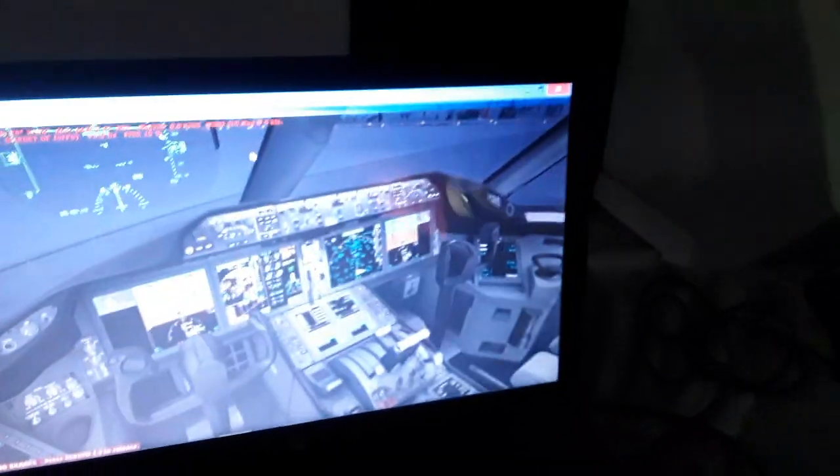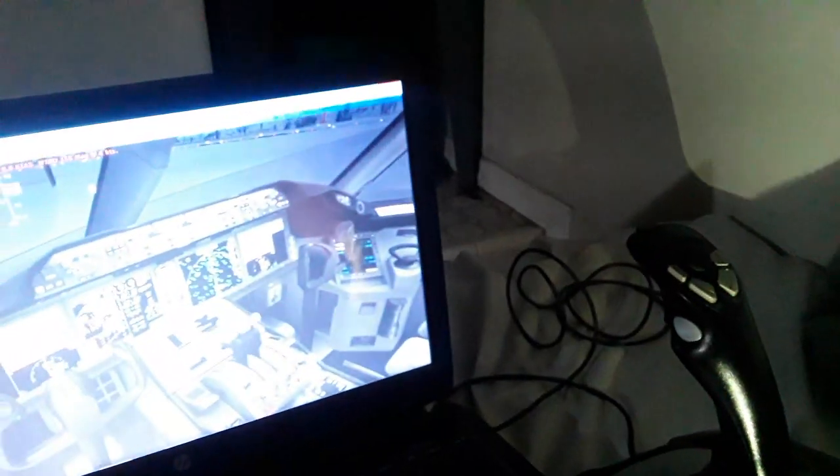So the fuel mixture adjustment is made automatically by the FADEC. Over here when you move the thrust levers, you command the engines automatically. So the FADEC also controls engine start and shut down. As I told you, fuel mixture is automatic, and also the circulation of the fuel, oil and lubricant from the wing tanks. When flying, the fuel is gonna be freezing at minus 37 degrees below 0. So we recirculate whenever it's needed automatically, again from the FADEC, using the recirculation from the fuel tanks to the